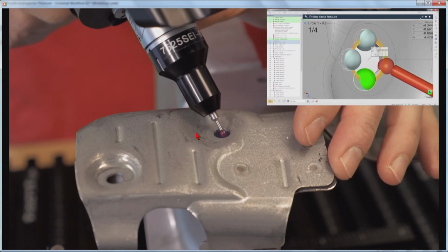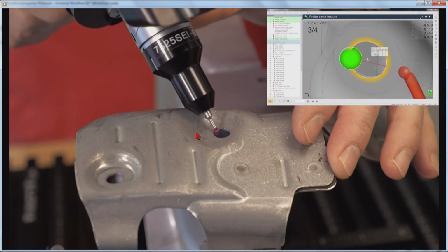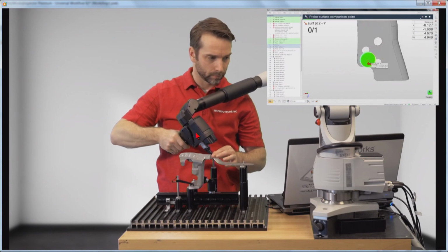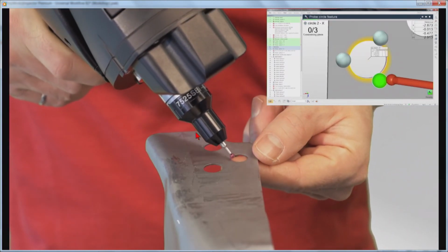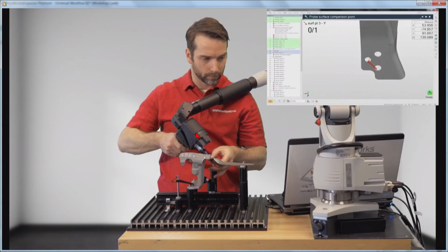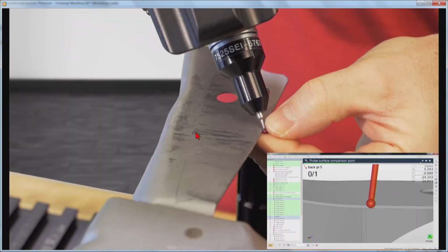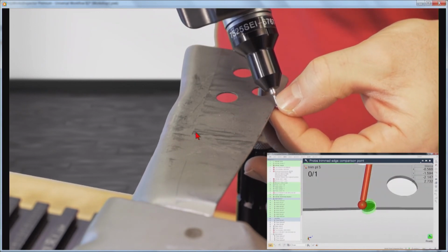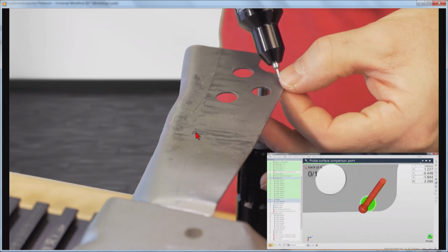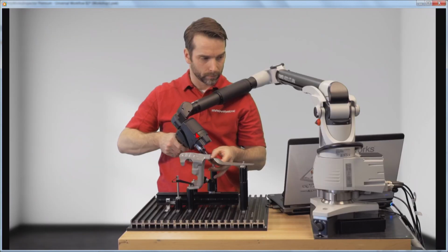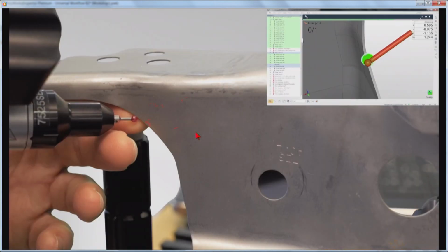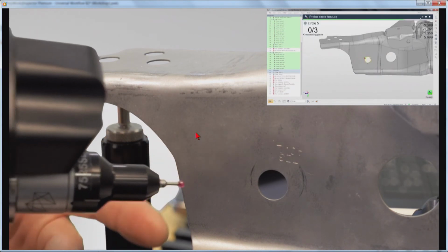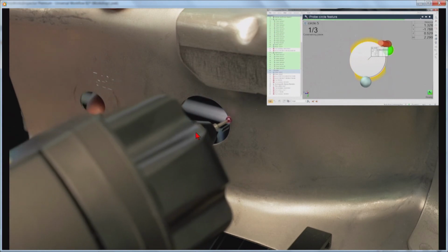So we're measuring our four-way circle using the same 4 points, and now we're measuring our surface points. Then I can go ahead and measure my two-way hole, and once this is completed, the alignment can be performed and we can continue measuring everything like the trimmed edge comparison points, the holes on the top, and then I will proceed with the remaining ones. Now, of course, all the tool orientation change steps do not exist anymore in this sequence, which is why things are pretty straightforward when you execute this on an arm.